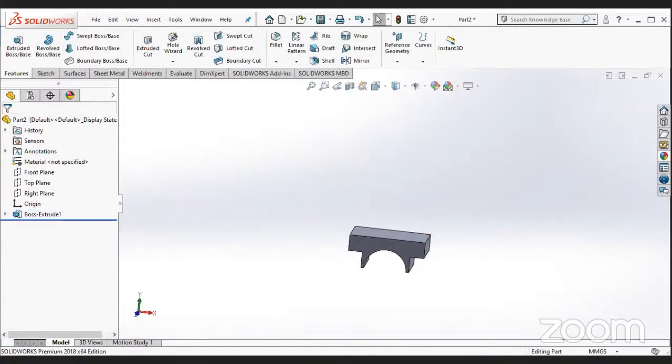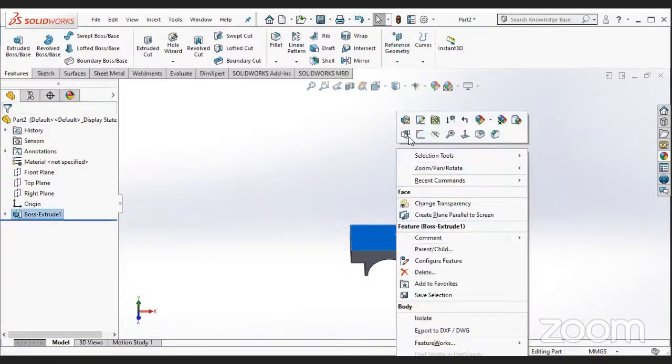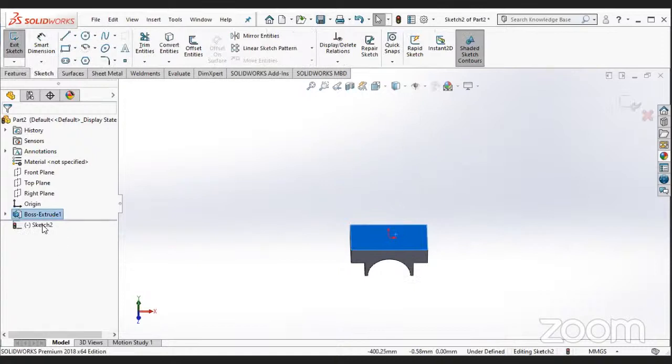This is our cap. We'll quickly finish it with the other remaining parts. We have a hole again. We'll quickly make the holes on 105 from the center line, so that will again be 52.5. You can select this surface, sketch on it.